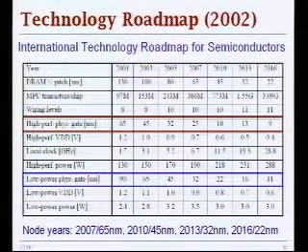And so now going to shrinking technology, you will also have to add more wiring levels. So in the quarter micron technology that we used in class, we have only 5 metal layers, but today in 90 nanometer, we have 7 or 8 metal layers, and due to increased complexity, you will have to add more and more levels for signal routing to be able to connect all the signals globally.